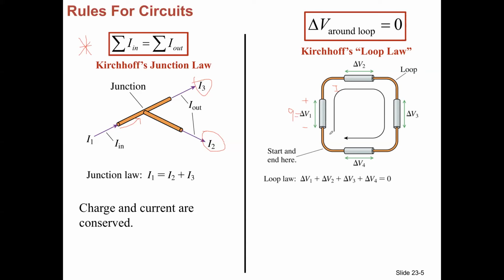and the battery is a 9-volt battery that gives all the charges moving around in this current some energy. That means that if these other things here are all resistors, as the current moves through these 3 resistors, it has to eventually lose all this energy it gained from the battery. So if these are all equal resistors, as the current moves through, it has to lose a little bit of voltage here, a little bit here, a little bit here, but all of these losses have to add up to 9.